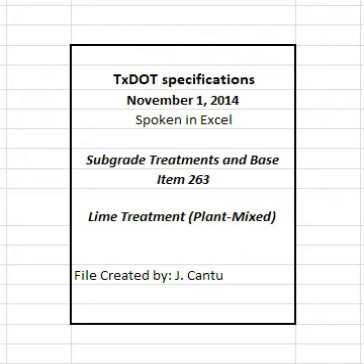Correct grade deviations greater than 1/4 inches in 16 feet measured longitudinally or greater than 1/4 inches over the entire width of the cross-section in areas where surfacing is to be placed. Remove excess material, reshape, and roll with a pneumatic tire roller. Correct as directed if material is more than 1/4 inches low. Do not surface patch. The 72 hours time limit required for completion of placement, compaction, and finishing does not apply to finishing required just before applying the surface course.